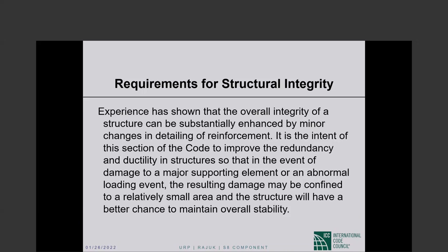So you will have special moment frame columns in your superstructure, and the transverse reinforcement requirements for the piles will be more relaxed. You will not have the very tight tie spacings as in the columns of the superstructure. What they are, without checking, I do not know offhand, but they definitely are relaxed. You do not have to provide the same confinement to the pile as you do to the column of the superstructure.